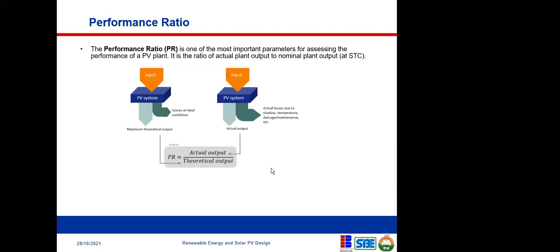So now, remember when I told you that when you have your PV system, when you look at the label, you're going to see the characteristics. So for example, you're going to see the wattage, maybe 300 watts, okay? It does not necessarily mean that when you install that PV system, you're going to get 300 watts. That 300 watts is at standard test condition. So if you subject your installation to standard test condition, you will definitely get 300 watts.